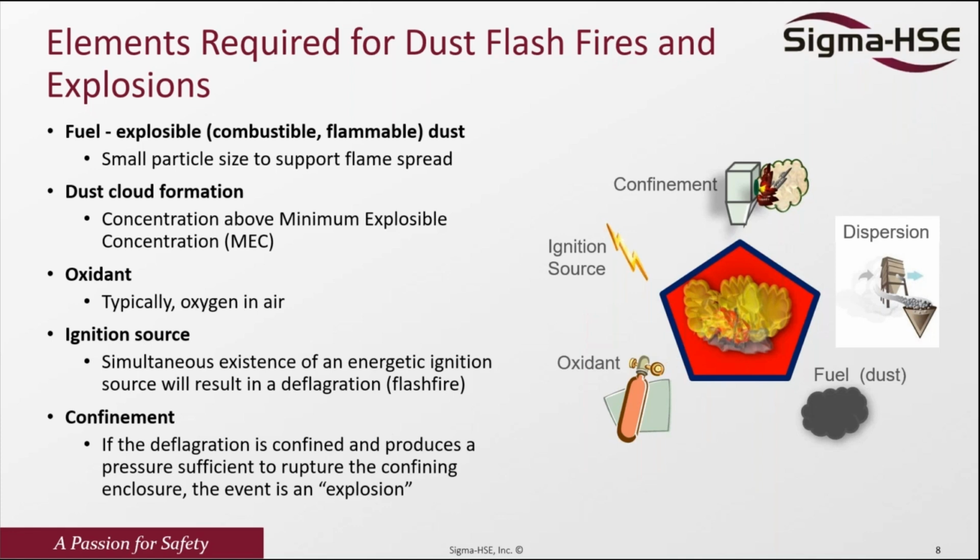But if you don't have confinement or enclosure, this energy release is just going to release to the atmosphere. So if I stay beside this combustion operation, the worst scenario is I'm just going to have maybe a burn, because the energy being released is disposed through the atmosphere. However, if I have a confinement, the energy being released is going to continue to accumulate, because there's no way to dissipate this energy.